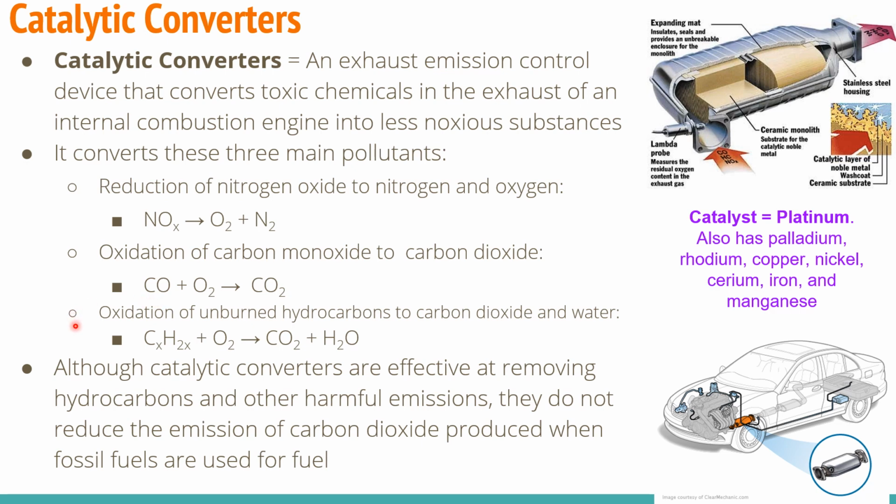And then the last type of reaction this catalytic converter does is the oxidation of unburned hydrocarbons into carbon dioxide and water. Within gasoline, there's octane, but there are also other hydrocarbons in this mixture of gasoline. It can convert that, in the presence of oxygen, into carbon dioxide and water.